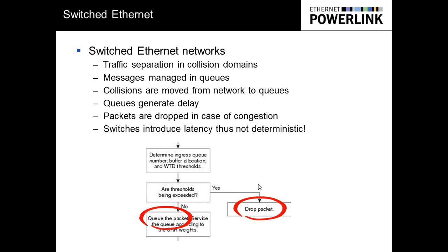So people introduced the idea of switches to industrial Ethernet. Well, a switch is designed to eliminate the concept of collisions. So a switch will guarantee that component A can speak to component B without any interruption. And if you have several components in your architecture, you need to know who talks to whom in advance, and you have to configure your switch. These are not unmanaged switches that you would go buy at Best Buy. These are switches that you have to configure manually and control, knowing in advance what your architecture is going to be like.